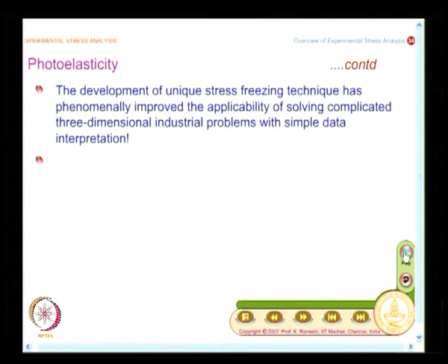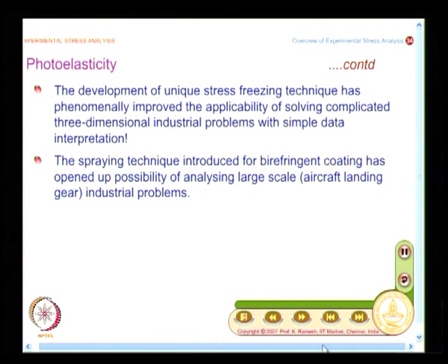A person who develops a design from fundamentals, he needs to go through experimental methods, he needs to worry about analytical understanding, he needs to use even numerical technique appropriately and arrive at a final design. And if you look at in early stages, 3-dimensional photoelasticity has played a very significant role, and particularly because of a very interesting phenomena called stress freezing. We will see that detail later. Now, you are being sensitized on what are the possibilities. So, this is what in the case of transmission photoelasticity.